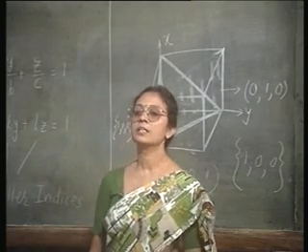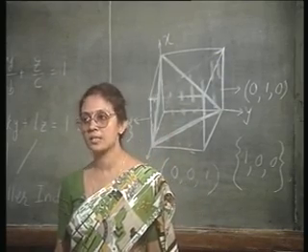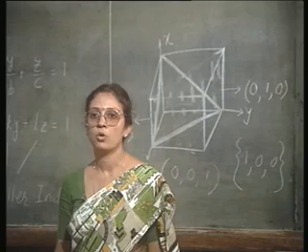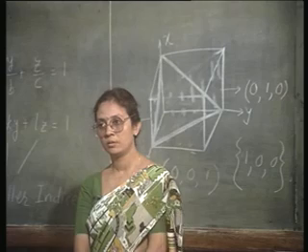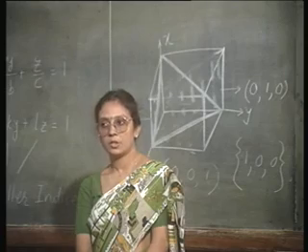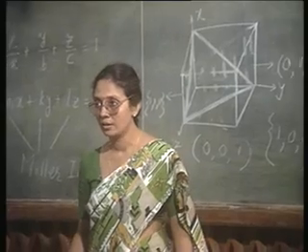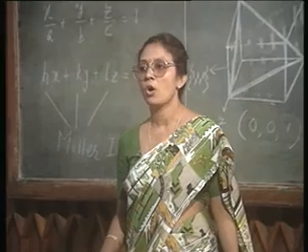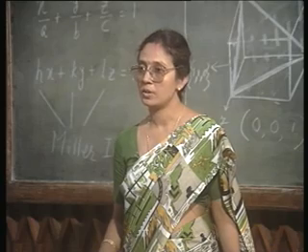So, they are the three basic families of planes we need to discuss when discussing the crystal orientation of silicon. They are 1, 0, 0, 1, 1, 0 and 1, 1, 1. Depending on the particular plane, the properties of the material will differ, and in the next class we will see how the properties of the material is going to depend on the particular crystal plane.